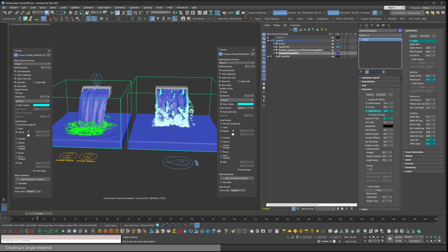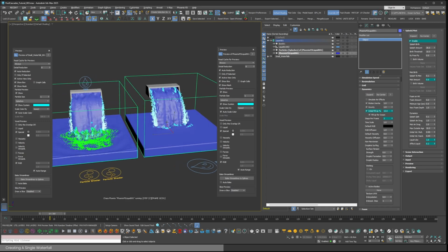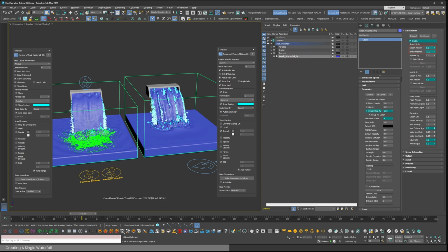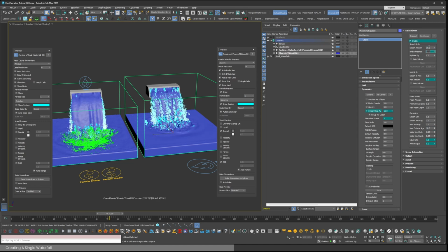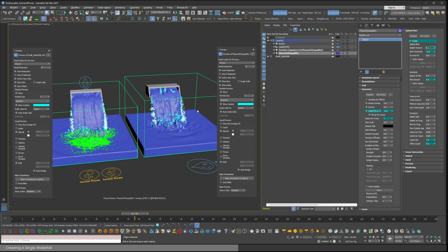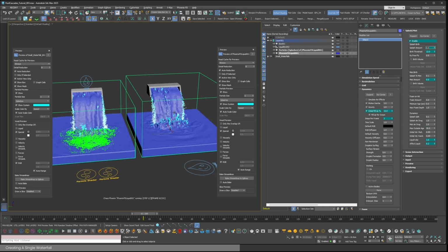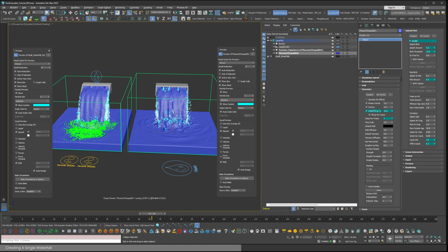It seems like I have a lot more splash particles in the second simulation, but that's not a surprise. I'm simulating it with only 2 steps per frame, and the flow isn't as smooth as the other one. But also, I think the left one has a higher birth threshold and produces fewer splash particles. Let me use the same threshold for the right one. Threshold 12, and the amount, what was it? 5. Right, with the same SPF, I believe the look will match even more.